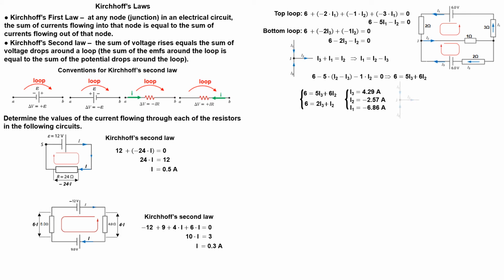Thus, as a last step here, we correct the answers by reversing the arrows for those currents and then rewrite the answers. Choosing the right directions of the currents at the outset is unimportant because the equations are linear, and wrong choices result only in a minus sign in the answer. This shows us that the initial choices are indeed arbitrary.